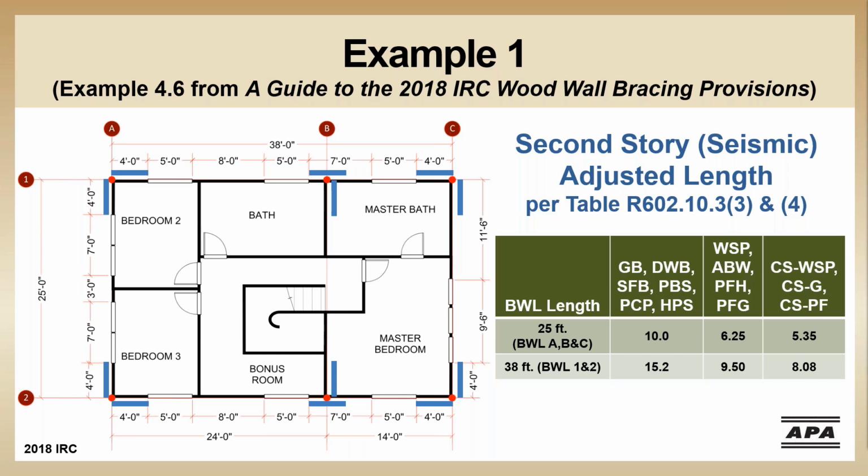This is going to be impossible at braced wall line A, since the 3-foot section left to us isn't going to meet the minimum length requirements for any of these methods listed in column 1. Braced wall line B, on the other hand, does have plenty of additional wall length available.